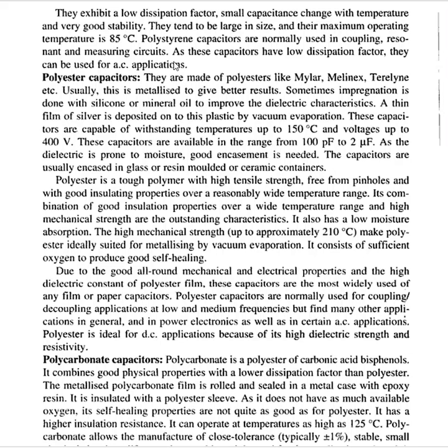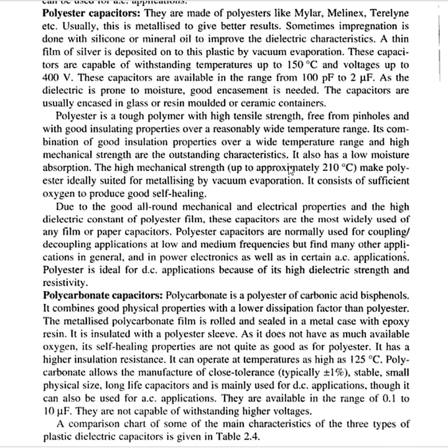The capacitors are capable of withstanding temperatures up to 150 degrees Celsius and voltages up to 400 volts. The capacitors are available in the range from 100 picofarad to 2 microfarad. As the dielectric is prone to moisture, good encasement is needed. The capacitors are usually encased within a glass or resin molded or ceramic capacitor.